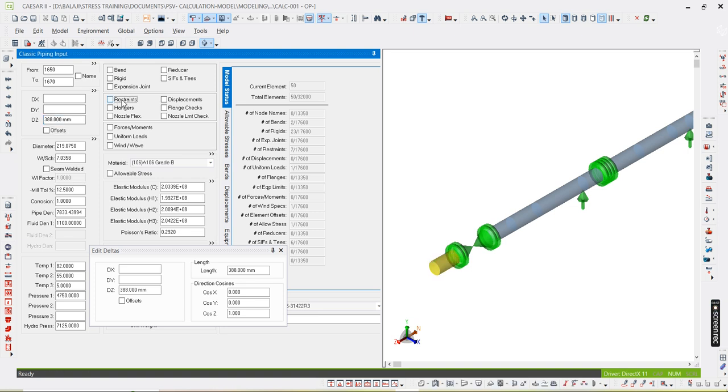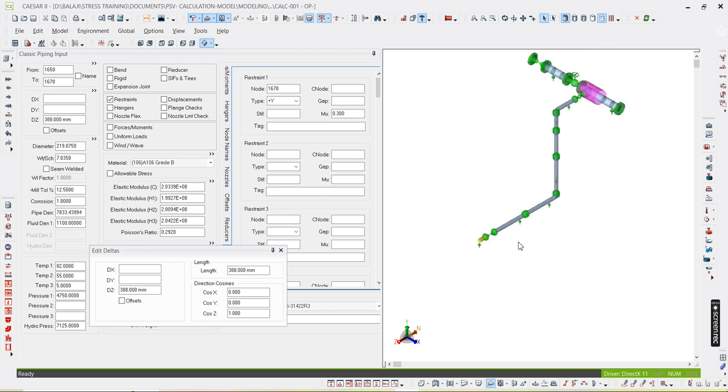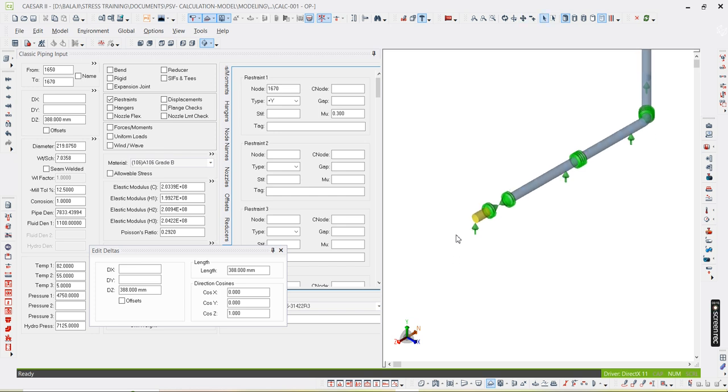So on support is there, you select here. These supports are very important. If they are not provided, after analysis you can suggest you have to add the support after the valve. Better for 8-inch or 10-inch above lines, before and after the valve, you have to provide on support.